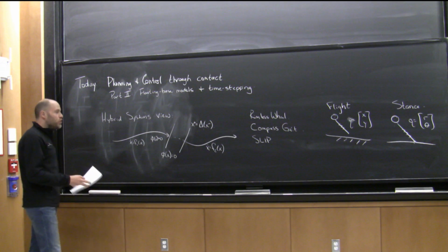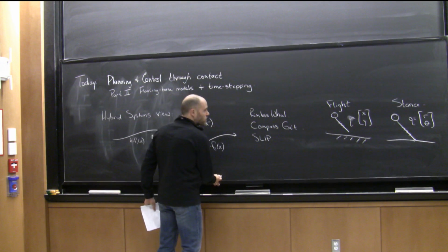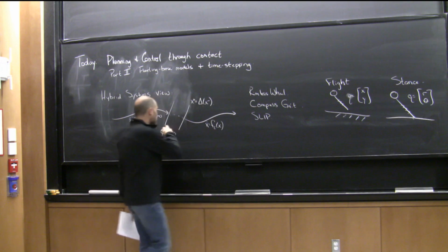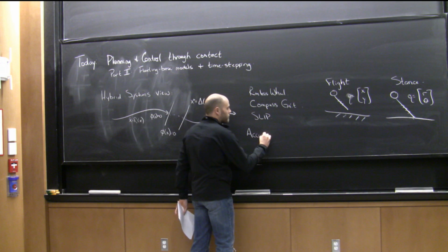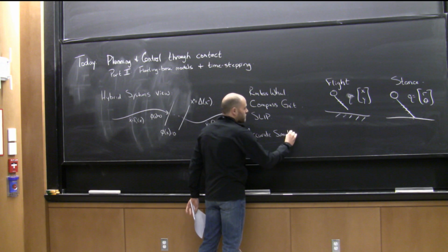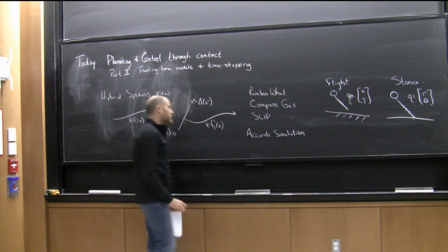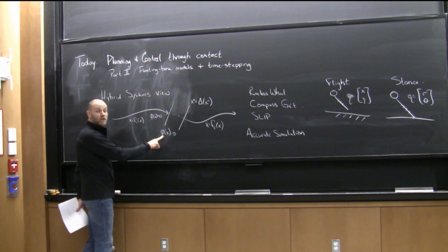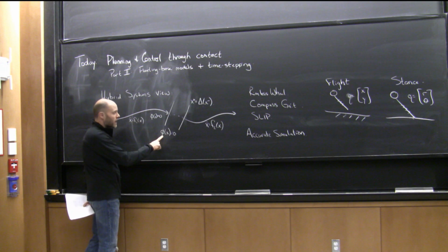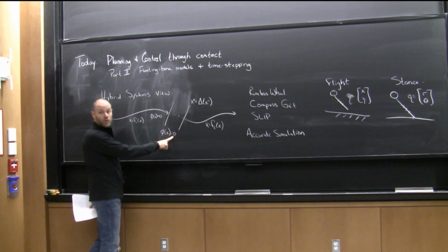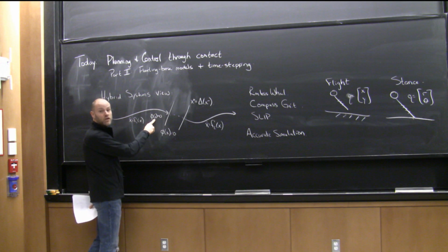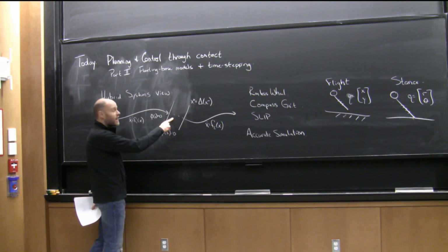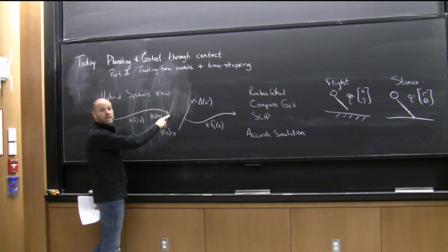You know, that's hugely powerful for a number of reasons, right? So first of all, in this paradigm, you can do very accurate simulation, right? Because if you specifically tell your numerical integration tools about the existence of this guard as a witness function, which is the language in numerical integration, it will, as it integrates, check the positivity of this function, check to see if it ever crosses that function, and then do explicit event detection to find the moment of zero crossing.